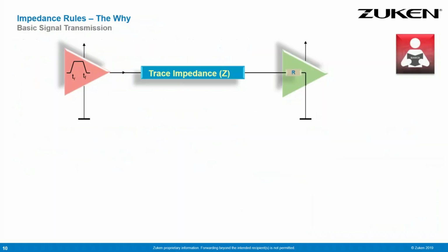of these structures. To understand what's causing a signal not behaving that well, let's dive into the basics. Let's dive into waveguide theory. So let's look into an interconnect where we have a driver and a receiver. The interconnect is modeled in a way that the driver can be seen as a time-dependent voltage source. So we do have a rise time and a fall time describing the behavior of the driver. We have the receiver, which can be seen, very simplified, as a high impedance resistive load.